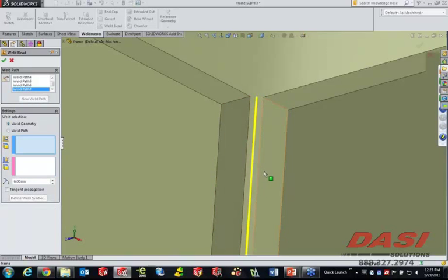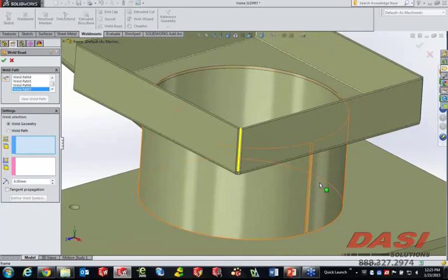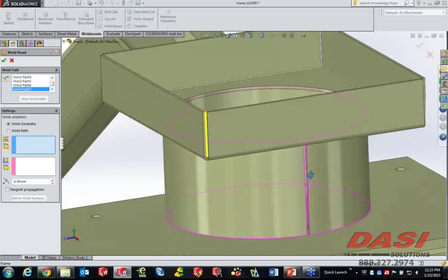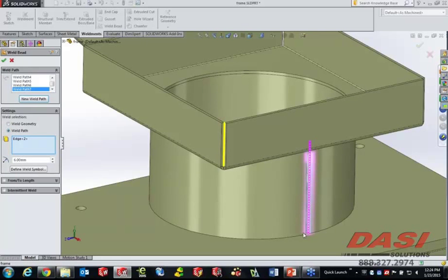Let's do one more new weld path, and this happens to be another one of those use cases. We have a rolled piece of sheet metal, which is again going to be welded back to itself. Well, here we actually can't use the weld geometry because we're only going to do a single selection. So we have a new radio button option that was added to the software called Weld Path. By simply selecting any edge of this vertical face, we're going to get a weld the complete length, and you can even do intermittent or stitched welds based on that edge selection.